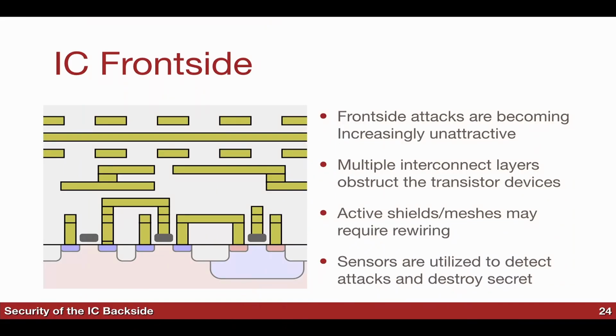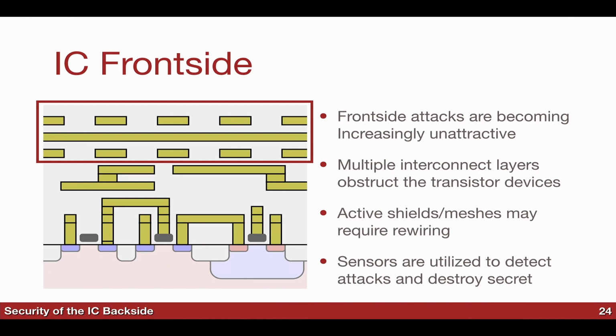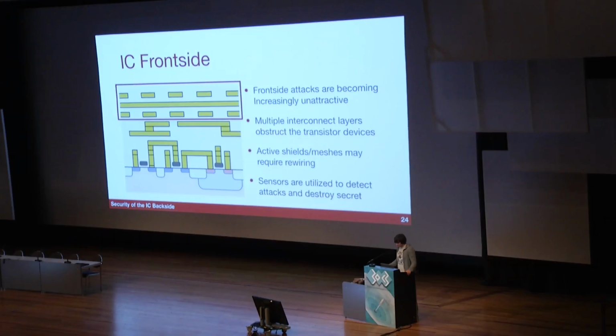Technically there are still ways around it, which Chris demonstrated at Black Hat in 2010 when he showed this on an Infineon chip, which had a lot of the countermeasures. But the thing is, it's still a nuisance. This is the image we had before, but the reality is you have something like this on a modern smart card, and what's completely irrelevant to the actual circuit underneath is this mesh, these protective layers on top. So that's why we want to flip the chip over and go in through the other side. We'll get into that in a bit.